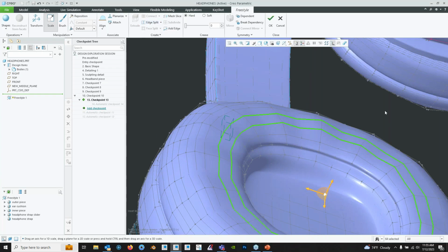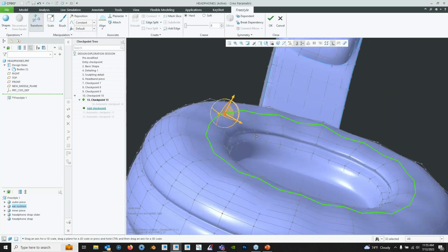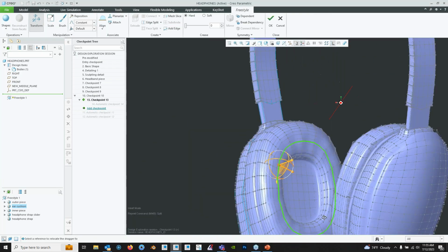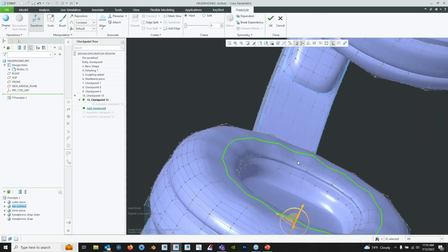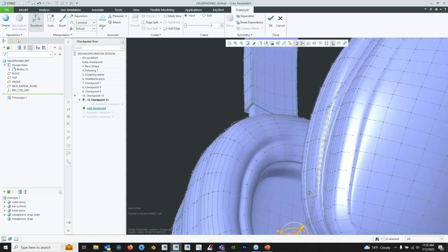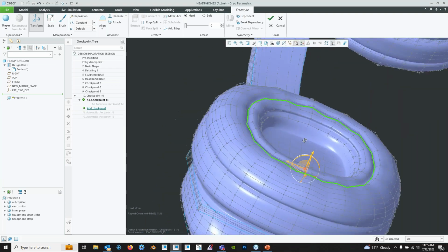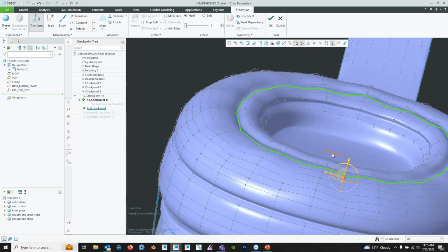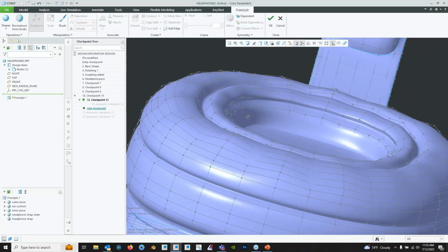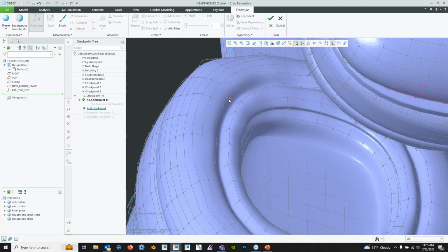I'm actually going to add one more edge loop within there, split, and I'm going to use the transform tool. I'm going to relocate this. I could pick somewhere that's more central on it. And as you're doing this, you'll notice that while you're moving it, it'll start to take its shape, and then after you're done it smoothes itself out automatically.